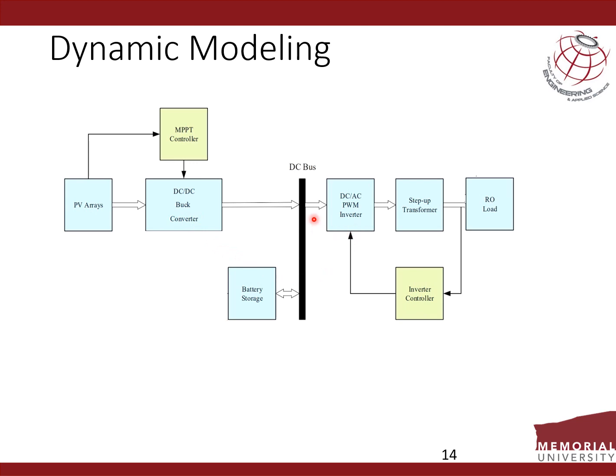Then we have to convert our DC voltage into AC since our load is AC one, as explained before. And you can see the inverter is just converting DC to AC, so the voltage should be increased to be suitable for the load, which needs RMS voltage value of 220 in 50 Hertz. So here we use a step-up transformer for